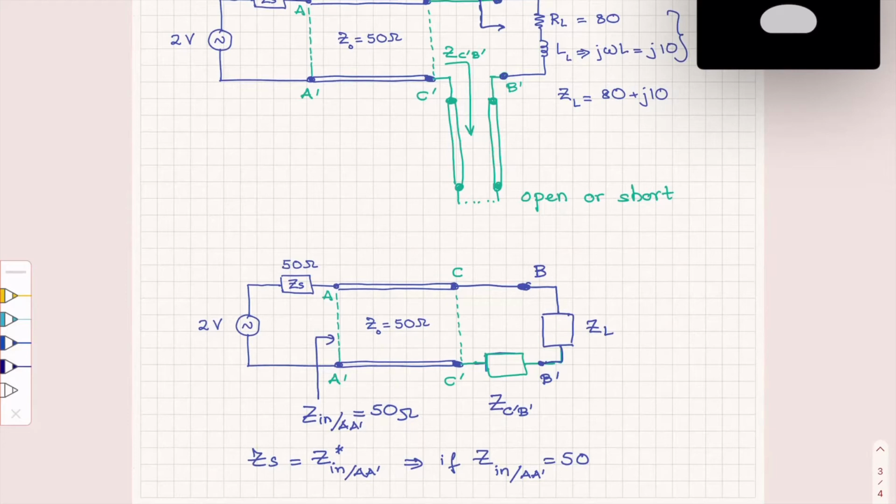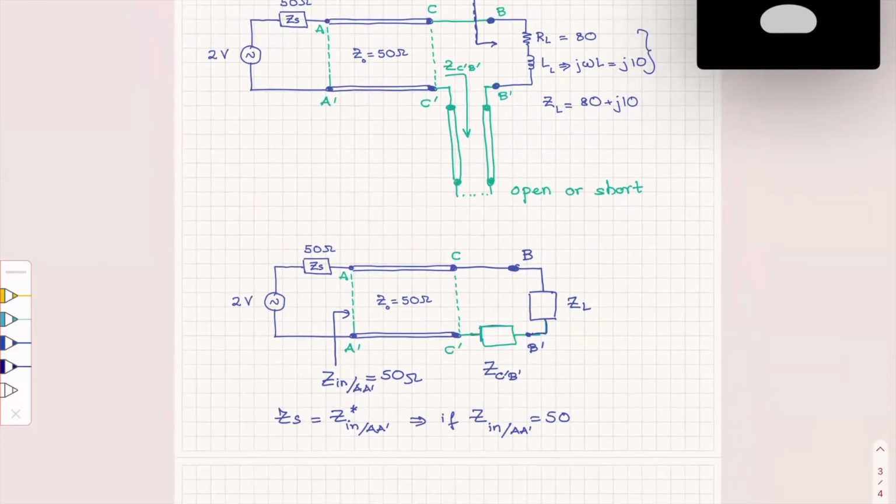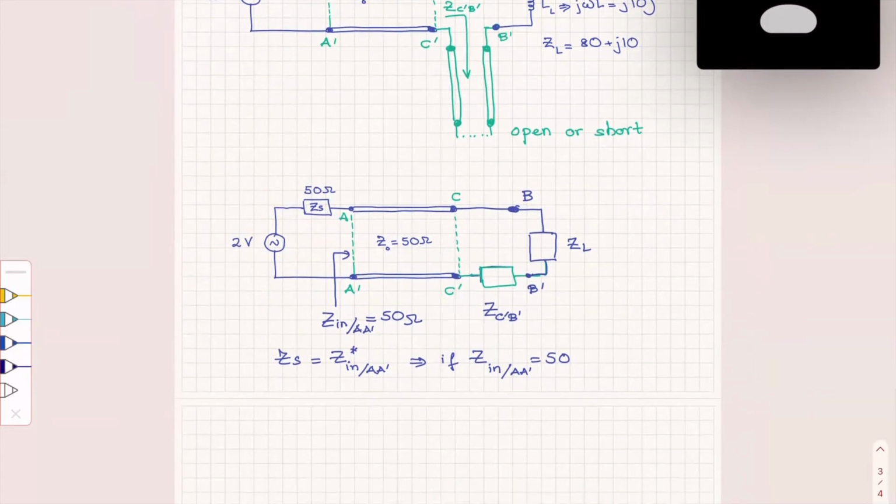Now, if I try to solve this problem the way it is, and let's assume that you want to solve it without the Smith chart, the only thing you can do by putting there a stub at the end of the line is, so the stub, observations, all right? So the stub is going to give me always an input impedance, which is reactive, all right? Always reactive.